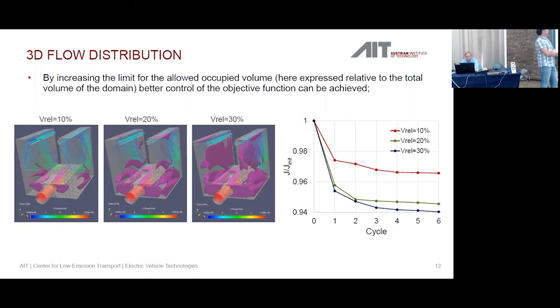But the idea here is that in all 3 cases, starting from the initial field without any porosity inside, you see that it doesn't make sense to update more than 3 times. So it solves primal and adjoint, puts in some sand, then updates velocity, primal and adjoint, and puts another sand portion, and after the 3rd time you see it's getting to a plateau, more or less constant. Okay, so in all three cases.